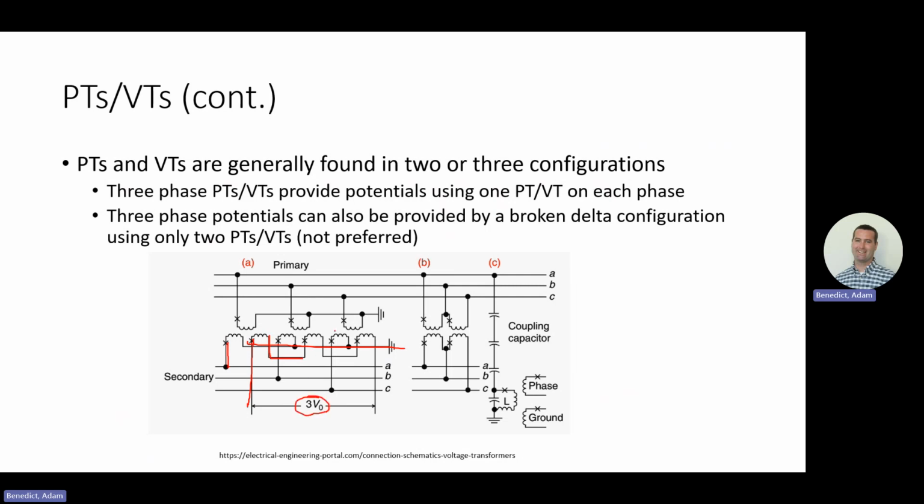It's used for definitely on... I see it most common on tertiary or station services that are ungrounded. So this would be how you would detect that ground fault. And then here's another configuration to get you those 3 phases. Not super common. It's generally if they're trying to save money on transformers. So usually you see this Y connection here.